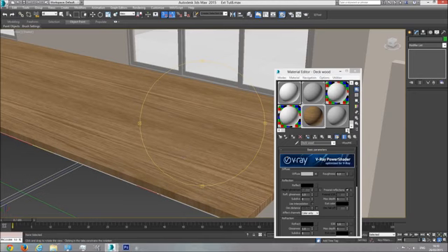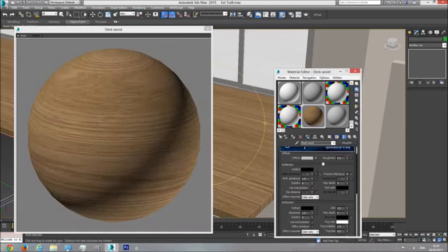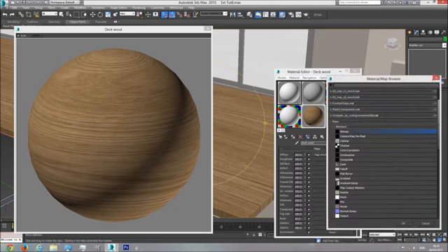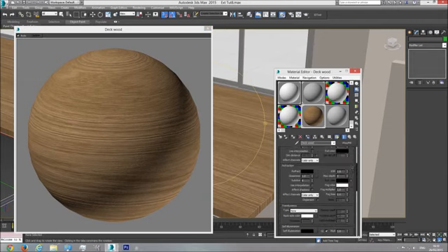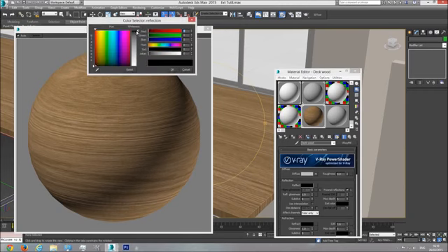and I want to give it a bump just a little bit to the material. So I'm going to go to Materials, Maps, Bump, and you know what? I'm not going to hit None. I'm just going to drag this to Bump, copy, and now as you can see you have a little bit of bump of the wood, maybe just less, like 20 here. It's fine. I want to give it a little bit of shininess or reflectivity, just a little bit, something like 50.